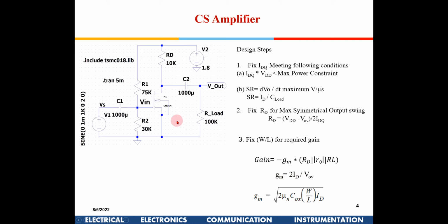So generally when an amplifier is made, the capital ID, VD should be much greater than the small signal and the small ID. Otherwise there will be linearity issues. Okay, so in that case you can neglect this VOV and follow what was told in the last class.